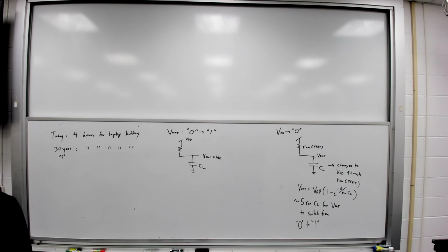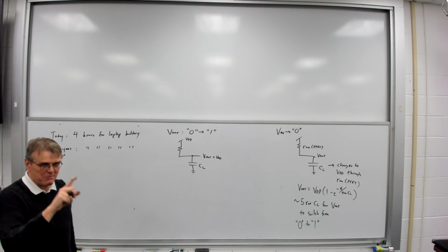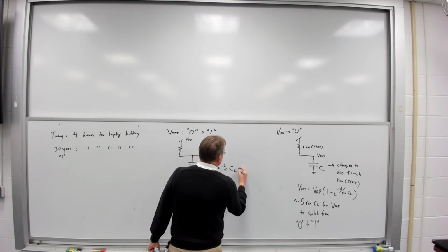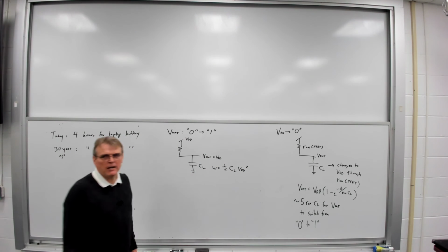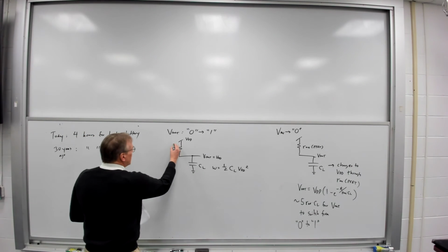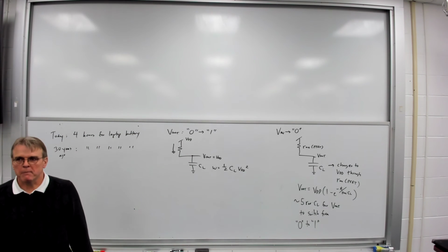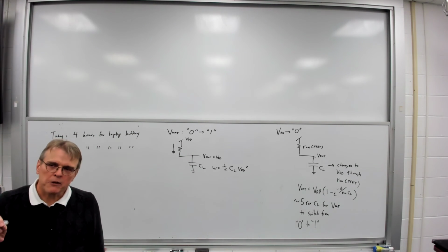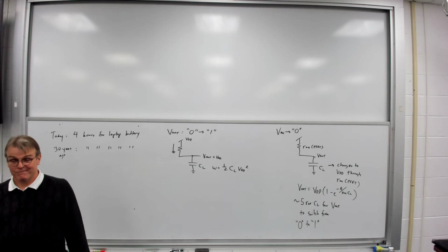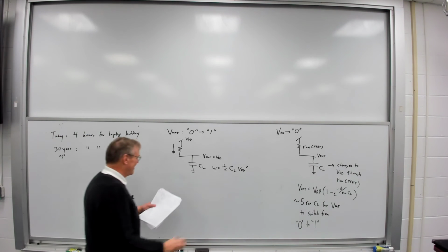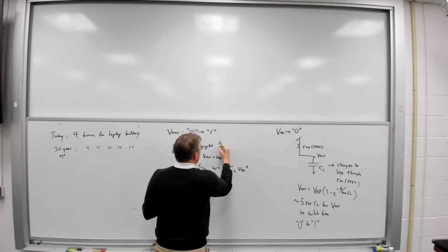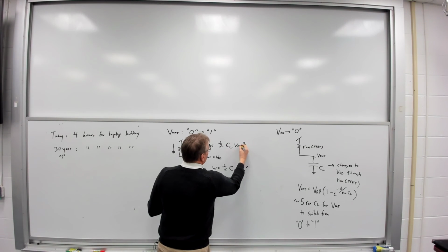2112 coming back to haunt you. 1/2 times CL VDD squared, right? The energy is equal to 1/2 CL VDD squared. You guys remember that? Now, while I'm charging up that capacitor, current is flowing through this resistor, and that resistor is dissipating power. Anybody want to venture a guess how much energy gets dissipated by that resistor during that charging process? Exactly the same. You can prove it to yourself. R on dissipates also 1/2 CL times VDD squared during charging.